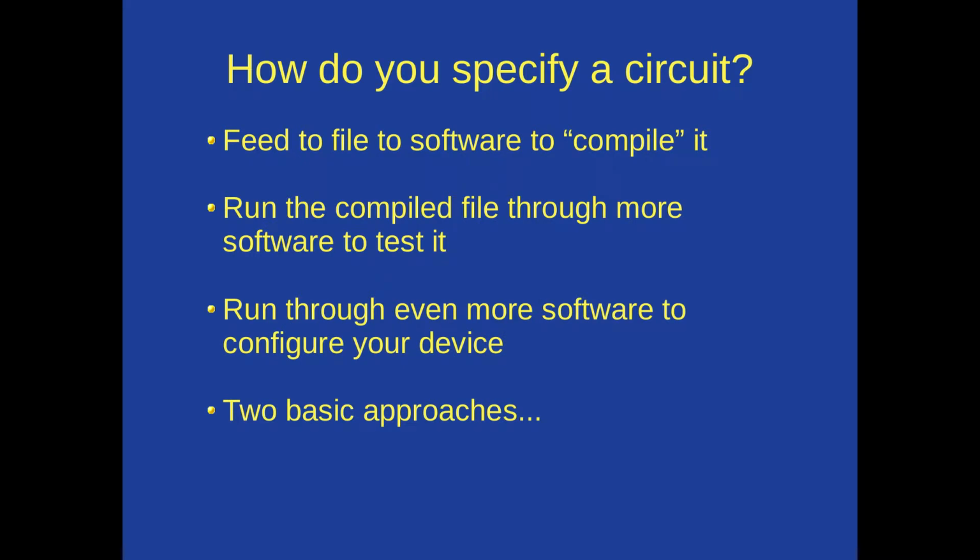So you take that file with your circuit description, you run it through something like a compiler for a regular software program, but it compiles it into an internal form, which you can then run into another piece of software to test your circuit. So you can stimulate the inputs, you can look at the outputs, you can decide whether or not it's working correctly. You can analyze the timing, how long does it take to change an output when you change an input, and so on.